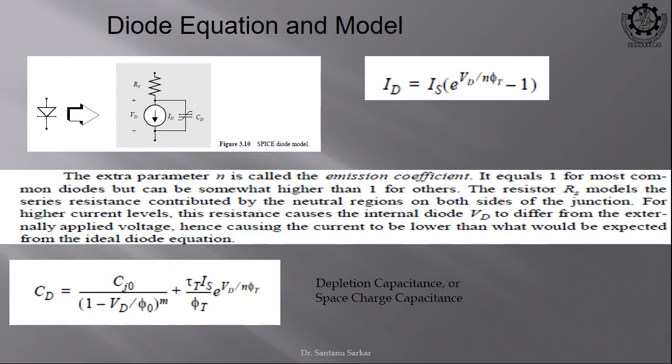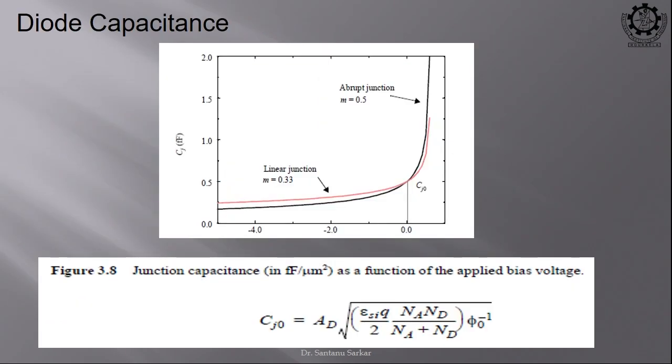So, generally in communications technology, they use this kind of varactor diode. They use this diode in reverse bias as a capacitance to tune the circuit.